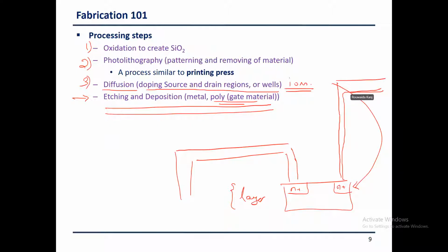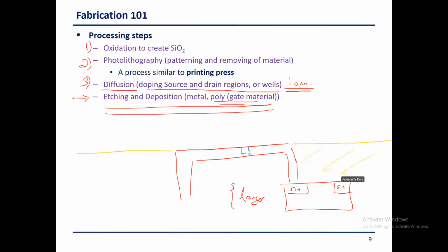Okay, so these are the different layers for the wire metals. If this is level 2 and this is level 1, for those layers to happen, we need at every layer to draw some insulator. After I print layer 1, I'm going to put a field oxide inside. So first, layer 1 gets some field oxide around it. It's etched with the field oxide around it. After I finish layer 1, I put another layer of field oxide, okay?